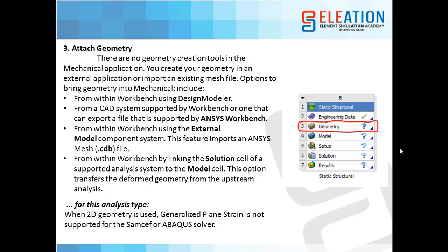Then we move to importing the geometry. We can import different file formats in ANSYS Workbench 17.0. This is the 1D geometry, so we import line data, and we add some options like checking the box in front of line data so my software can understand this. I have an IGS file format which has line data.